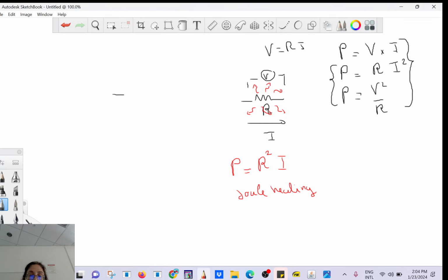If you want to decrease the amount of heat, you have two ways to do it. You can decrease the resistance or you can decrease the current. And I will show you two situations. Now, the other thing you want to understand is that each time you have a connecting wire, for example, here I have a connecting wire. Do you see how the wire is very, very long? That's going to increase the resistance, and of course it's going to increase the loss of energy. I'm going to lose more energy to heat because my wire is so long. Any connecting wire has its own resistance.